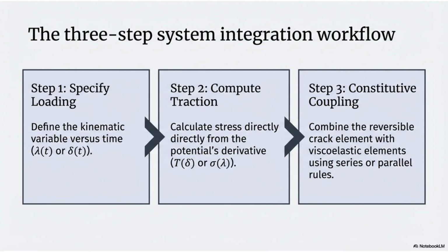The system integration workflow involves 3 steps. Step 1, specify loading, defining the kinematic variable over time. Step 2, compute traction, calculating stress from the potential's derivative. Step 3, constitutive coupling, combining the reversible crack element with viscoelastic elements.